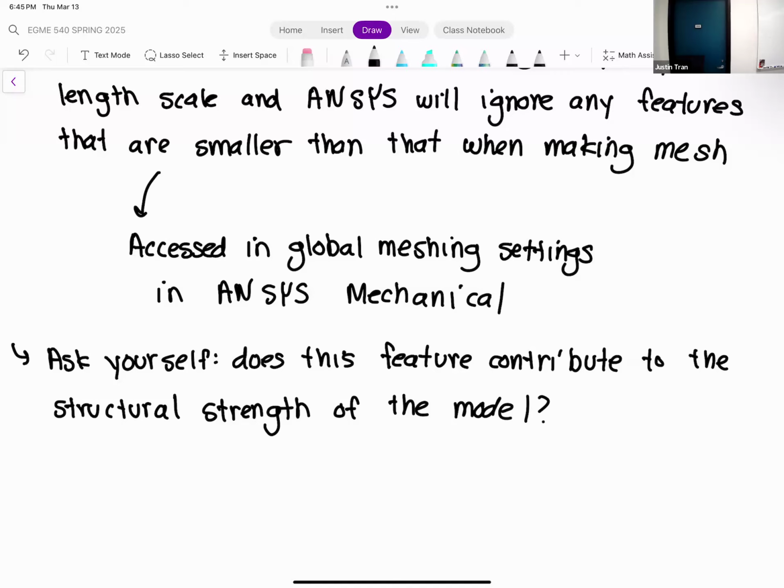Yeah, this looks good. I think the other thing that people are concerned about is the stress, because the stress is all concentrated here. If you change this to a fixed support, then the stress is going to be more even. Everything else looks good.